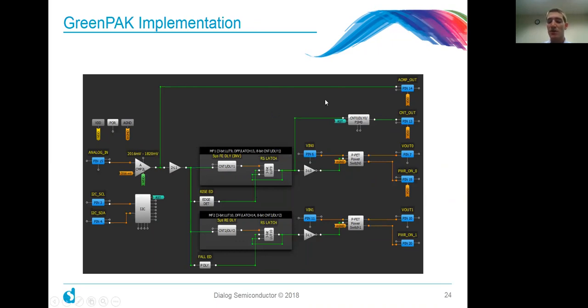If we count these phases, we also have an I2C block that allows us to read back all of the counted value. So as it increments naturally, you can go back in and read this value so you can determine the state of charge at any point in the battery's life cycle by a quick I2C read, which is really pretty cool and actually very, very simple.